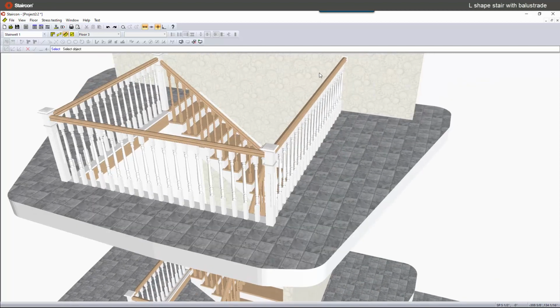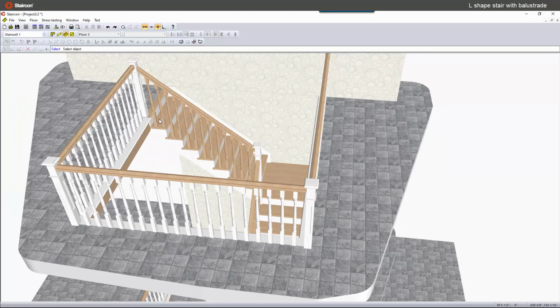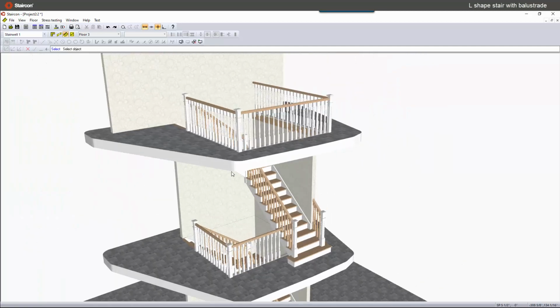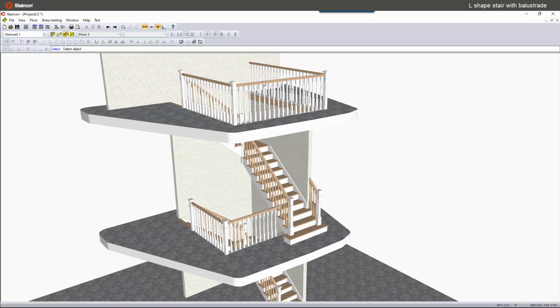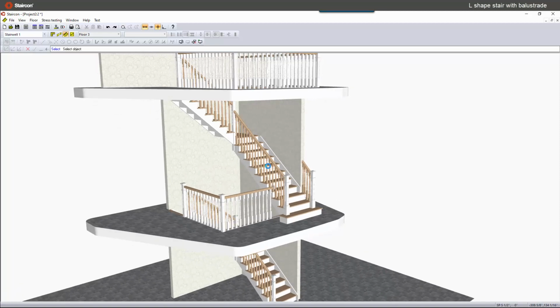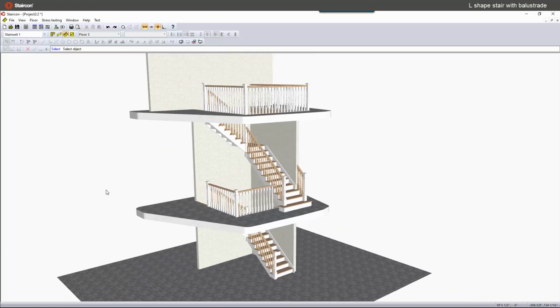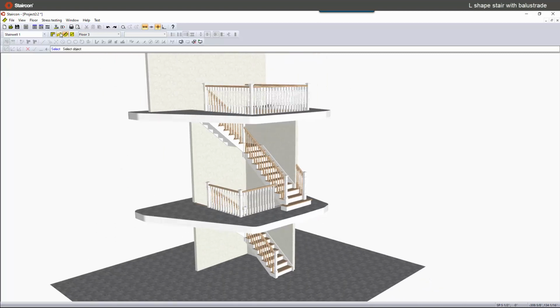So we got our balustrades with, now all of this you can set up in the database to do it automatically in the way how you want it, and also the material and finish override we can set up. So I didn't choose that for the stairs. So you see for the balustrade on the floor, we have an override for the balusters. But even if you now consider that this stair is good, but you want maybe, let's say, metal balusters, I can also change this on the fly and even go to pattern. Maybe I show that as a last thing, and then I guess we got a good example.